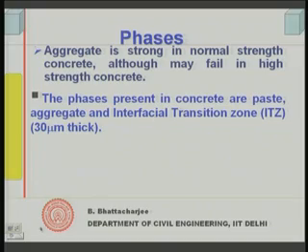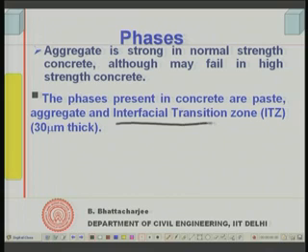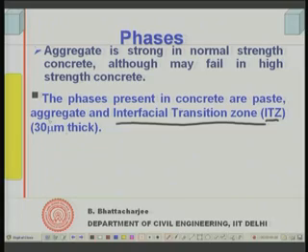the aggregate mortar interfacial transition zone. It is the aggregate paste and aggregate mortar interfacial transition zone, particularly the aggregate paste interfacial transition zone. Okay. And this we abbreviate as ITZ, usually of the order of around 30 micron thick as shown, 30 micron thick, right, and this is quite often treated as a second phase or third phase.